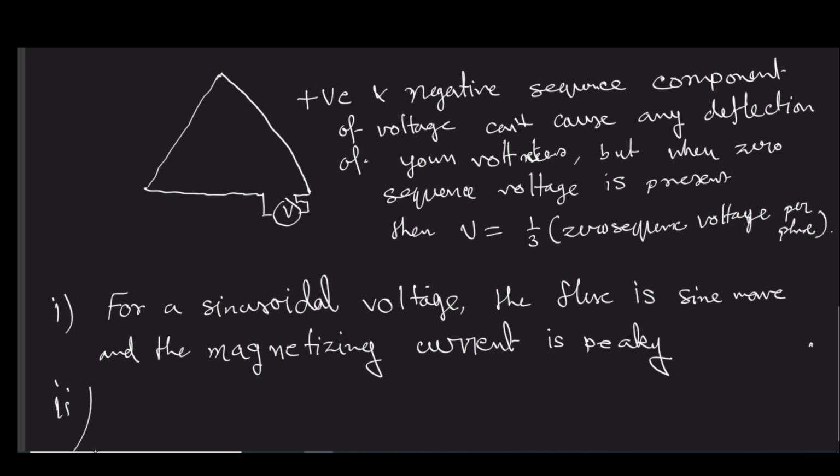So for all sinusoidal voltage, you can read it like when you have a primary transformer, that is primary side connected in delta. In case of delta, what we know is that line voltage is equal to phase voltage, and if your line voltage is obliged to follow a sinusoid pattern, then obviously your phase voltage has to be a sine wave. There is no other choice. However, the story is different for star connection.